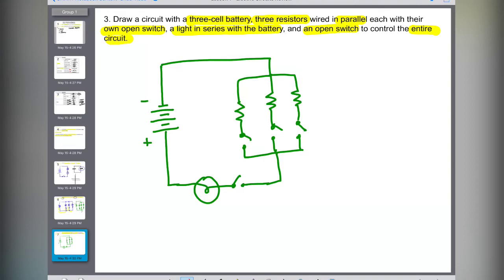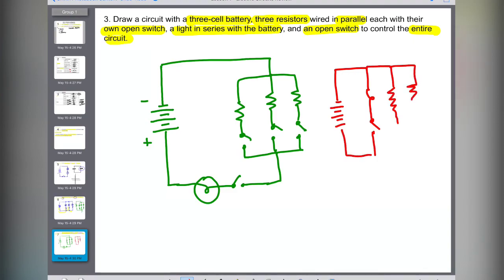Okay. The only thing that is not fine, well, there are maybe other ways too. I don't know if I'm missing it. Some of you might draw it like that, and then you would have your light bulb and your thing going here, and then thinking that that's in, and then your parallel resistor. This one is no good, okay? Because when you connect it like that, you've actually turned it into a parallel. So right now, your battery is actually parallel to the light bulb. Okay, so you cannot do that. So this is not good.